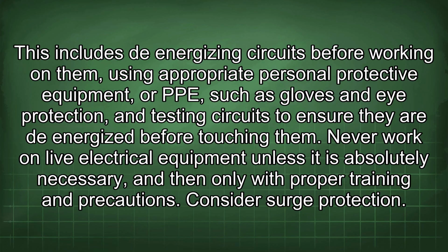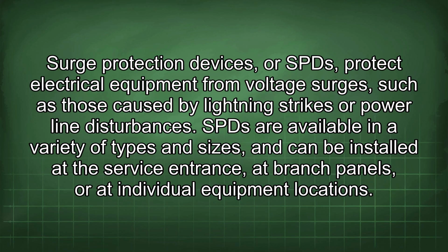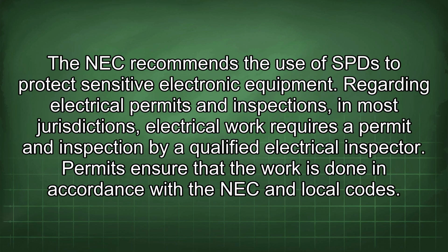Consider surge protection. Surge protection devices, or SPDs, protect electrical equipment from voltage surges such as those caused by lightning strikes or power line disturbances. SPDs are available in a variety of types and sizes and can be installed at the service entrance, at branch panels, or at individual equipment locations. The NEC recommends the use of SPDs to protect sensitive electronic equipment.